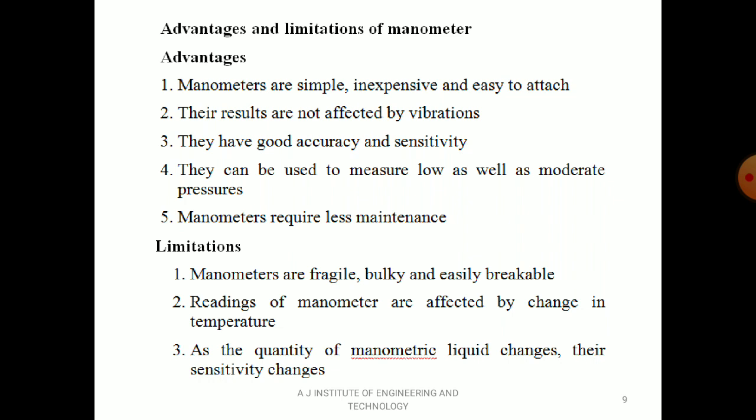First one, manometers are simple, inexpensive and easy to attach. It is very easy to fit the manometer, and these manometers are simple and inexpensive when compared to other pressure measurement devices. These have least cost. Second one, the results are not affected by vibrations. You can use these manometers in vibration environment. That is not going to change pressure values.